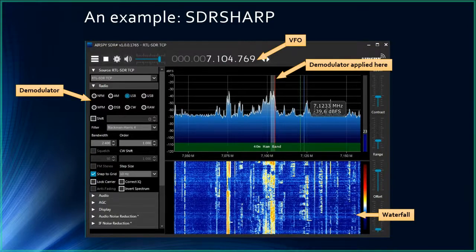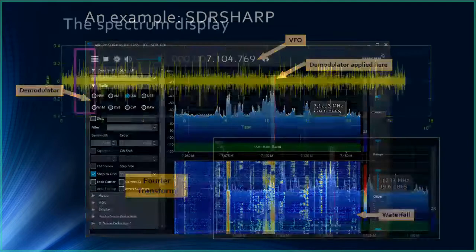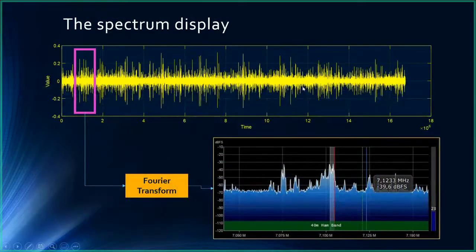You've seen that the signal the software is receiving is a series of values, a series of voltage measurements taken at a constant rate, and that's just what the software is receiving, nothing more. So that's the first thing, which is quite obvious now, is that this is time domain. That is to say, the USB cable is carrying time domain samples, arriving one after one.